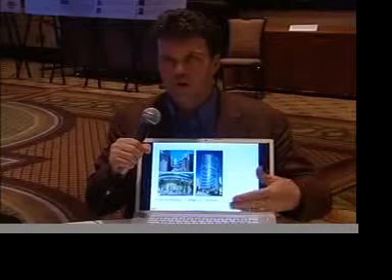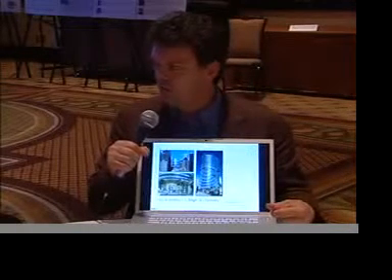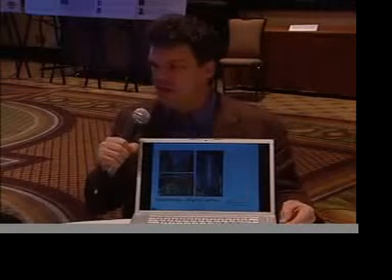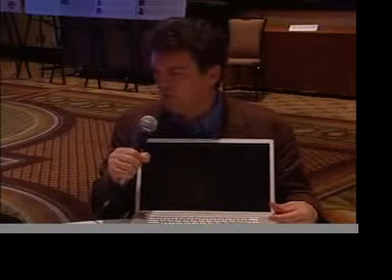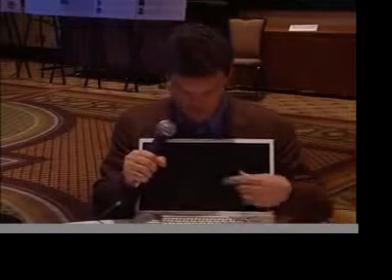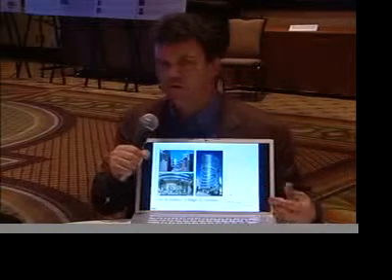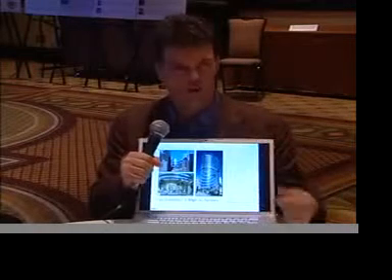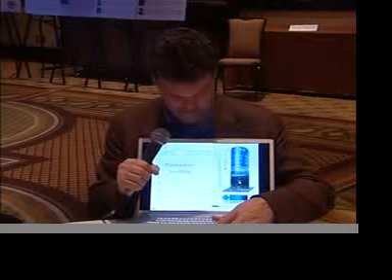And so we're actually extracting from the sewer to have enough water for the cooling towers. And this is one case where that's necessary. In other cases where there's a high proportion of residential apartments, you can generate enough from the base building because of the showering load. So you can generally recycle as much as possible from within the building itself.